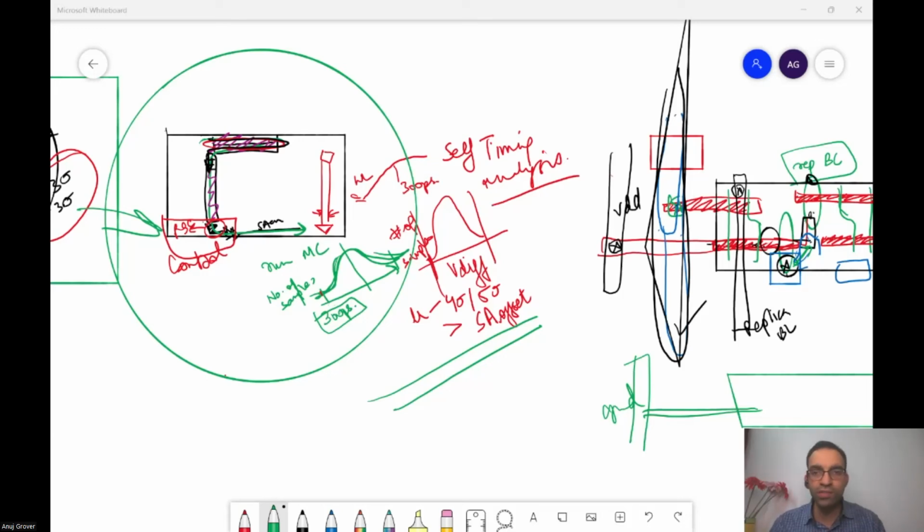The first question in the office hours today was, do I need to make one bit cell or an array of bit cells? I said there is nothing like one bit cell in an 8192 by 32 memory. There is a whole range of memory cells. There are 512K memory cells that we are talking about. So we should be able to identify what other parts we are directly depending on. I want you to learn that aspect also. Okay, sir.